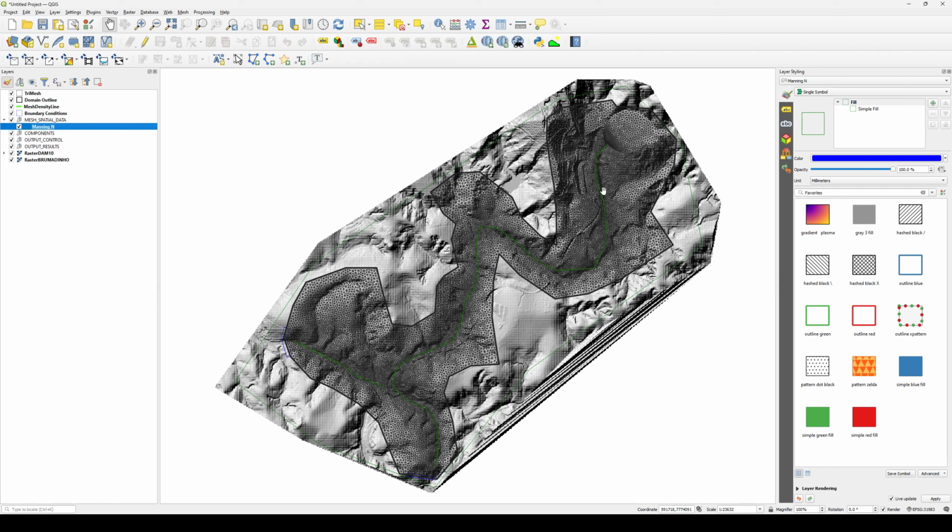So the next part would be to let's try and get this model running with the basic tailings model, just to get a feel for where all the flow should be and to make sure that our inlet is generating our river correctly and so on. So let's go ahead and click on the export files to RiverFlow2D drop down and click on the export to RiverFlow2D button.